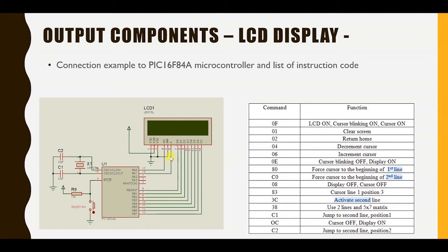And then the way the LCD works is you output the data in port B. Here in this case we have B0 until B7, so the data is in 8 bits. You send it through the line, and then when you press enable, it will go through.